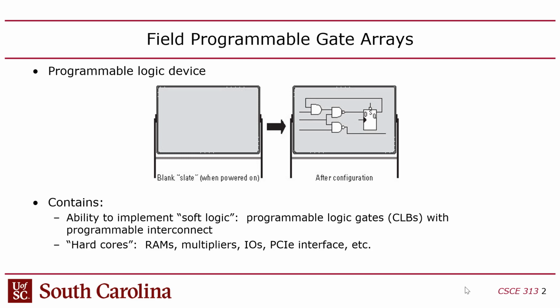Yes? So when you're talking about fabricating a chip, you mean as opposed to digitally configuring this, you could just have it constructed with that logic circuit built in? Yeah, so the distinction I'm making is between an FPGA and an ASIC, which is an application-specific integrated circuit. An ASIC is fabricated through applying masks to a silicon wafer in a fab.